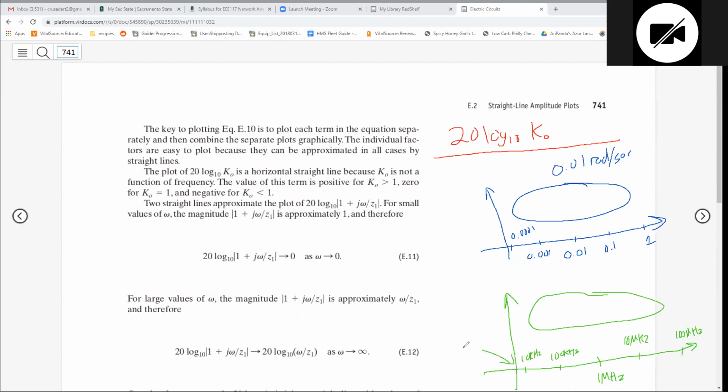Like right here inside, I don't care about what happens at 1 hertz and 100 hertz. That's outside the range I care about. So by using a log scale, we're shifting all the action to the area we want, in this case, 100 megahertz. Okay, so that's kind of why we're using a log scale. It lets us magnify the areas of information we want and the areas we don't care about. Okay, so does everybody understand log scale?